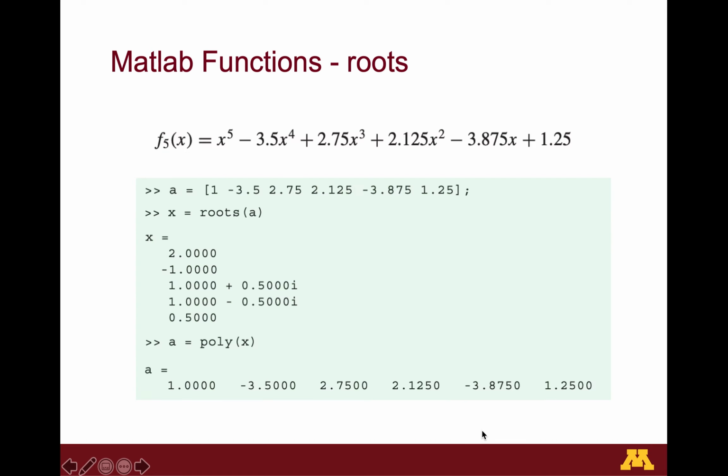Another built-in function is the function roots, which you are going to use again in a later course, process control and instrumentation. Given a polynomial f(x), we can form a vector with the parameters of x to the power 5, 4, all the way down to 0. Then we call the MATLAB built-in function roots to get the solution. If we call the built-in function poly, we can build back the polynomial equation. Pay attention, this function only works for polynomials.